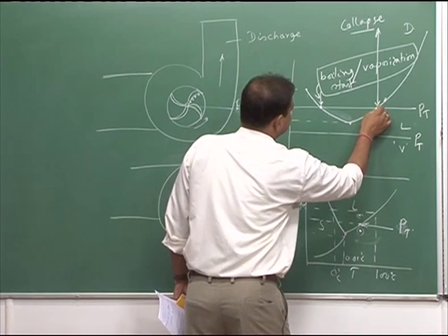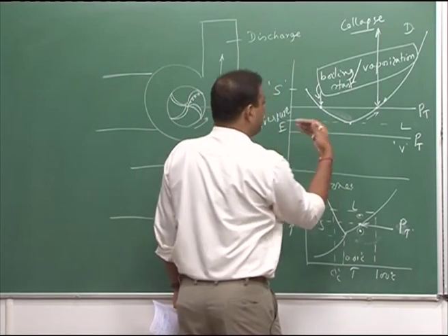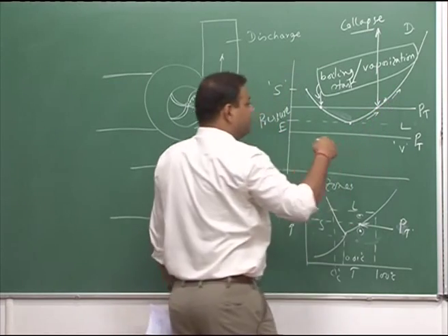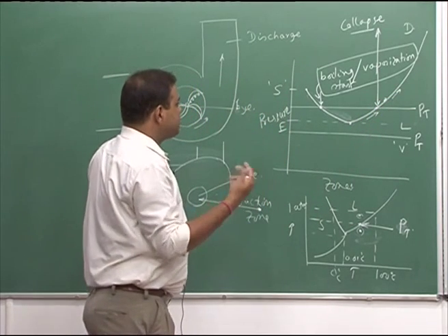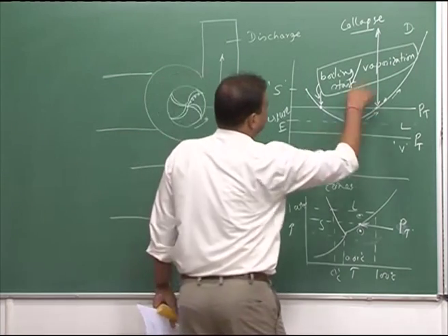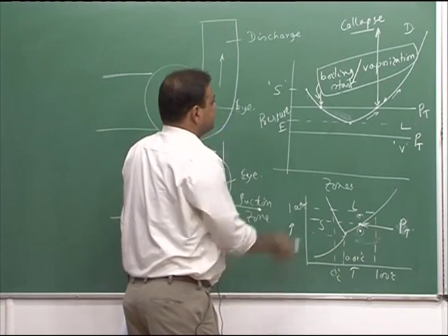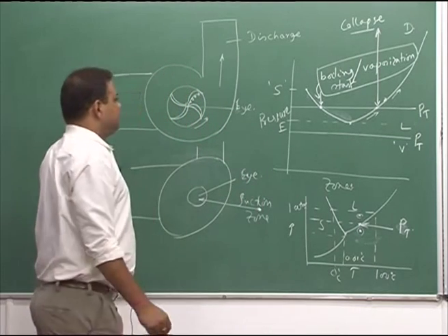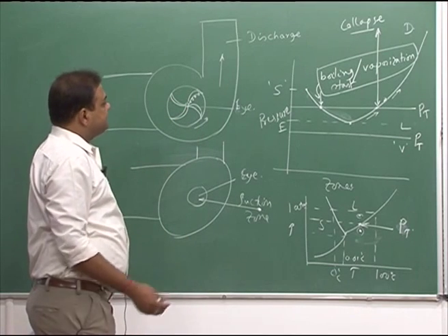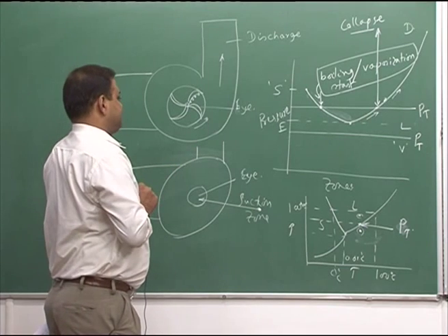Finally, when it reaches this place, the reverse cycle would start, all the bubbles would try to collapse, and when it goes to this level, in equilibrium there should not be any boil or any vapor. So, all the bubbles would try to collapse, and the shock wave generation and cavitation damage. This is basically the actual thing that is happening on the impeller metal surface, and that leads to cavitation damage on the impeller metal surface.